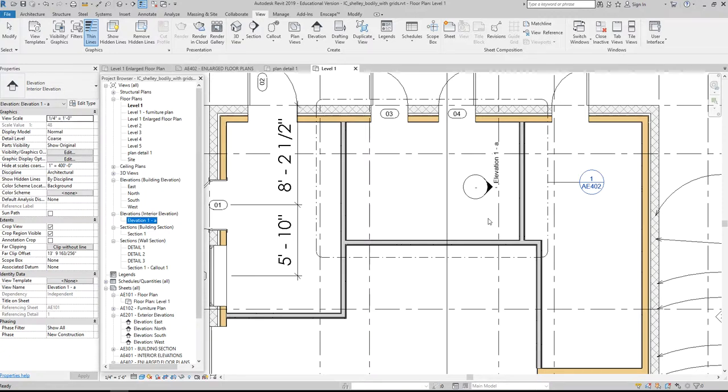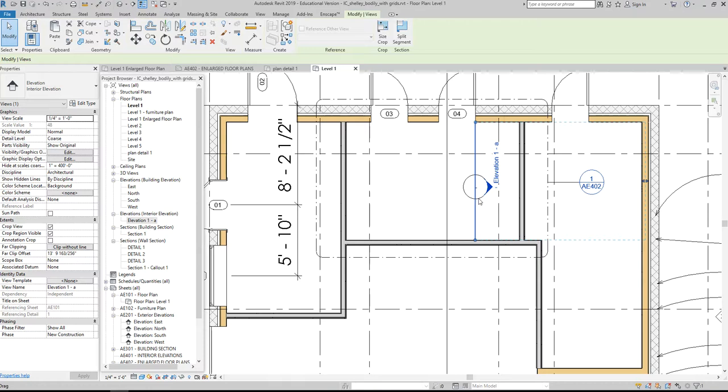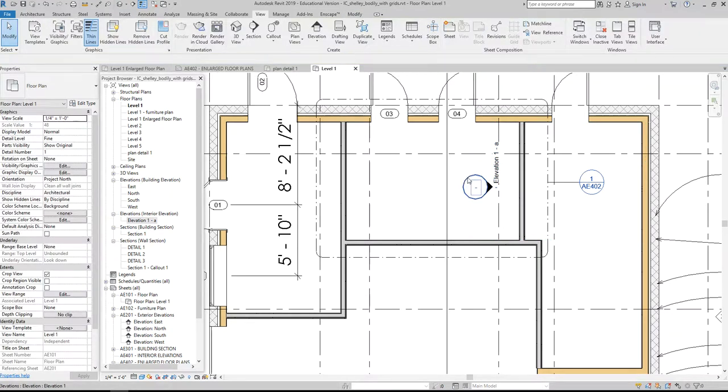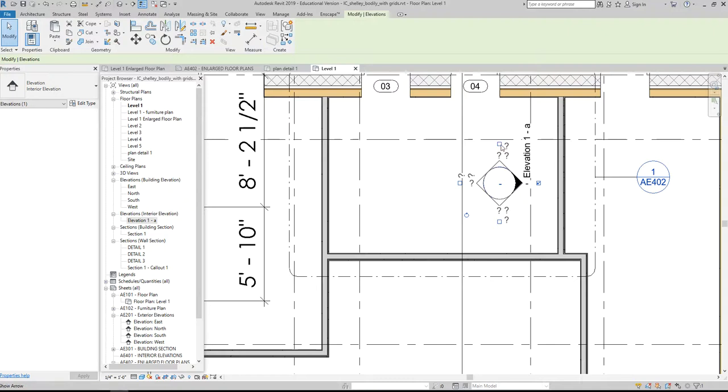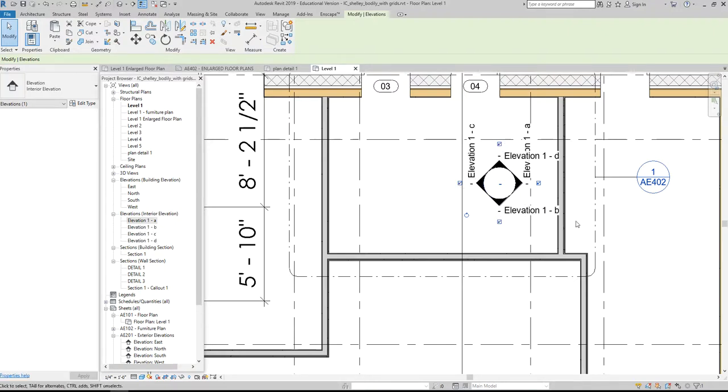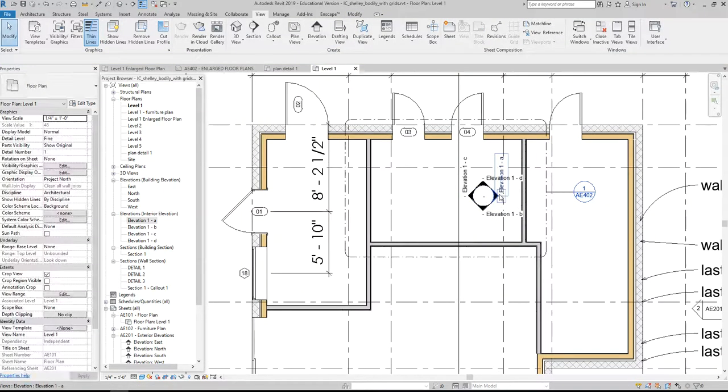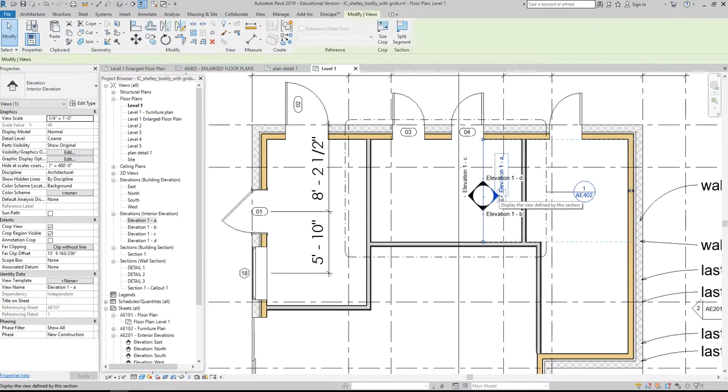which is pretty nice. If I click on that marker, the actual round part of the marker, this piece, you'll notice that I have these little check boxes, and as I check, oh my gosh, it's generating interior elevations like crazy. The interior designers should be going nuts right now, right? Have you ever been a new intern and had to generate like 400 interior elevations in AutoCAD? It's maddening.